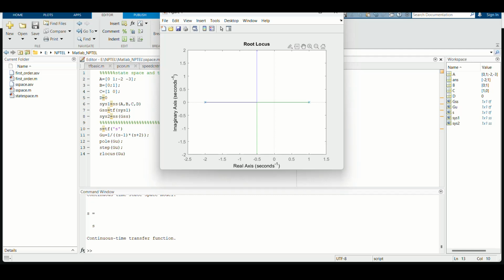Okay, so in the root locus, we can see that it starts from the open loop poles at 1 and -2. Then, as gain k is increased, it shifts to the LHP. This line is the partitioning line between the LHS and RHS. So for this value of gain, if we click on it, at gain 2.19,